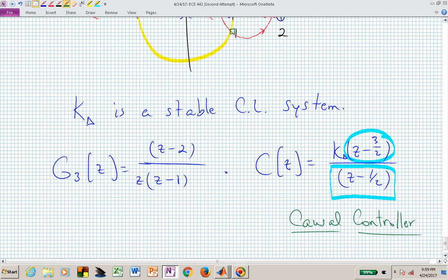And that's where I would like to finish with this transfer function based controller design approach. We've done the Ragazzini, we've done PID, which you can think of as proportional, PI that gives us this nice steady state error capability, and the PID, which allows us to not only have the nice steady state error because of the integral term, but the derivative term allows us to adjust the transient behavior.